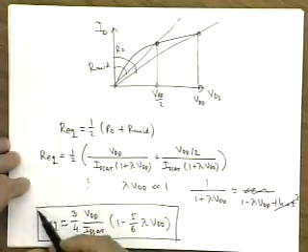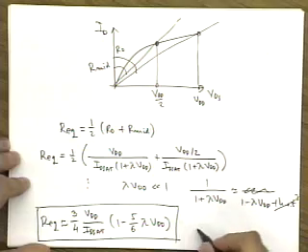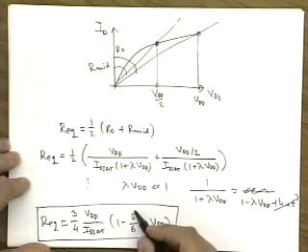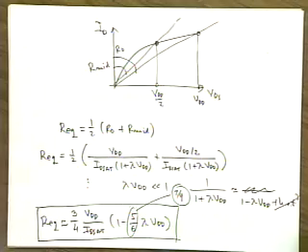In the previous calculation, where we had to solve that integral and average over the entire interval, instead of this 5/6 we had 7/9. The difference between 5/6 and 7/9 is not that much, especially since you have 1 minus that factor times lambda VDD, which is fairly small.